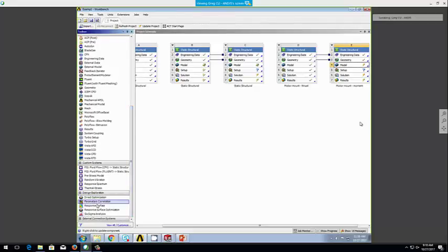So the VN diagram exists for various aircraft configurations and flight conditions. The manufacturer will have to satisfy the FAA requirements for clean aircraft, takeoff and landing. They'll have to go through the whole range from minimum flight weight up to maximum flight weight. We'll just look at the subsonic version. Of course, they'll have to consider the transonic versions for commercial aircraft, supersonic versions for military aircraft. We're just going to look today at the clean configuration, flaps and landing gear retracted, and maximum takeoff weight for the aircraft.